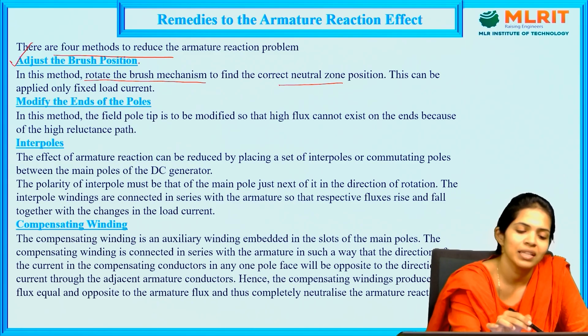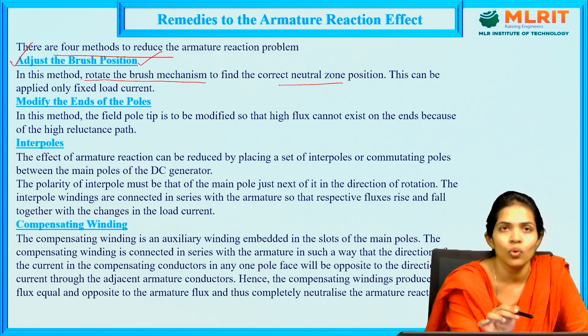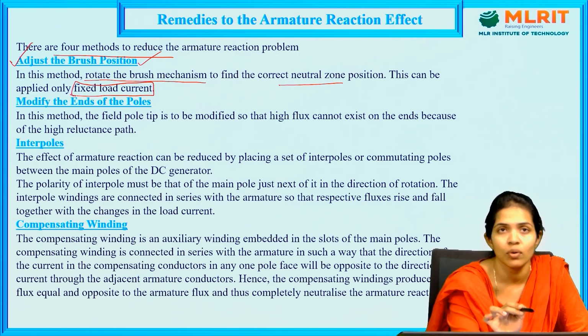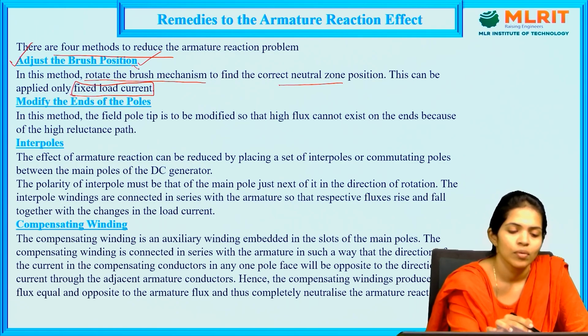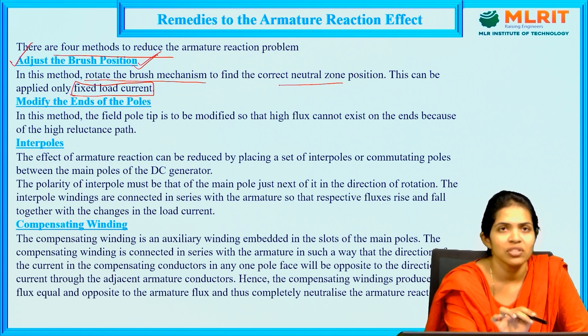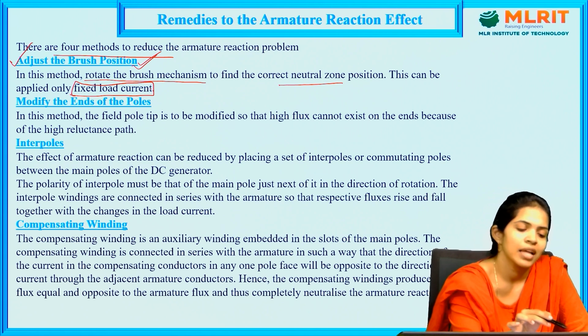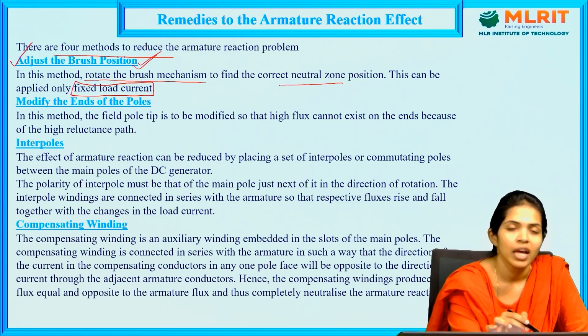Basically, this method is applicable only to fixed load currents, which require only a fixed amount of current without varying load currents. So this method of adjusting the brush position is only applicable to fixed load currents. And then moving on to modifying the ends of the poles.